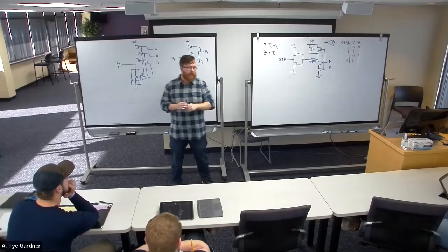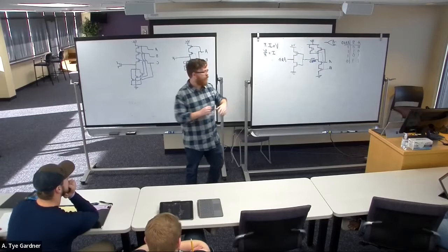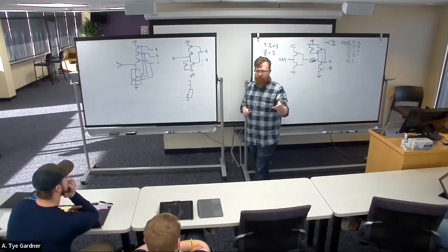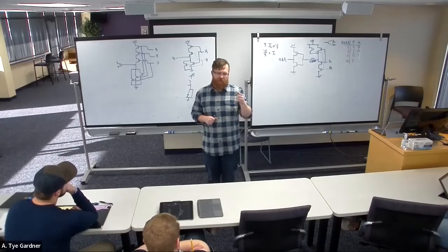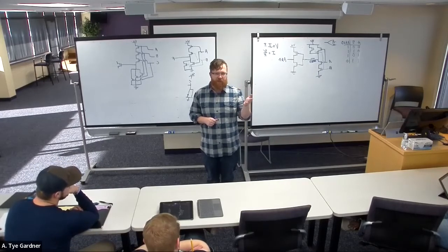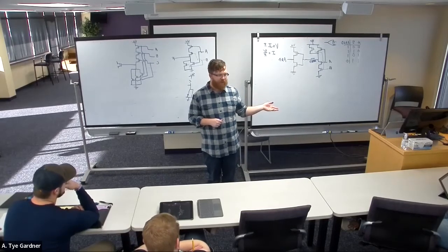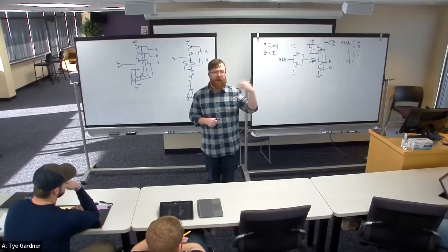I skipped a part. This is the problem when I don't print out my notes. You're going to have a device that you're talking to and you only get 2 wires. One of them is ground because you need something to be referenced to, and one of them is signal. And they need to talk to each other back and forth, but there's only 1 wire.